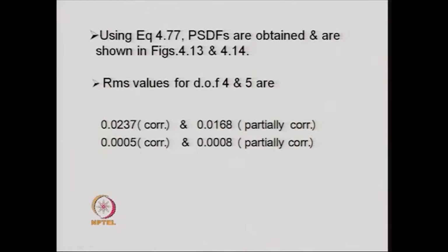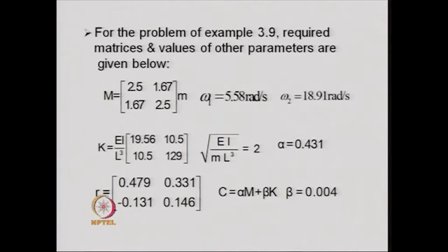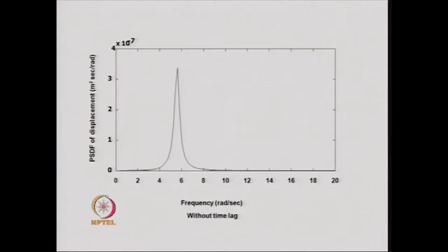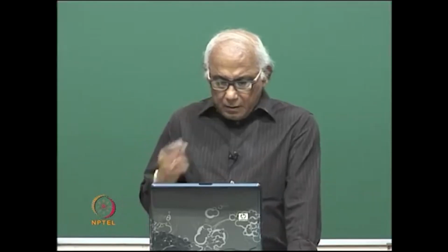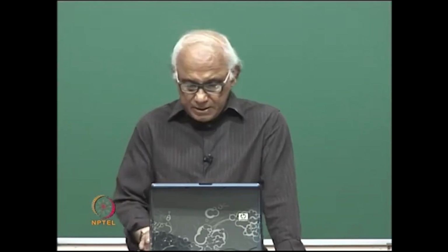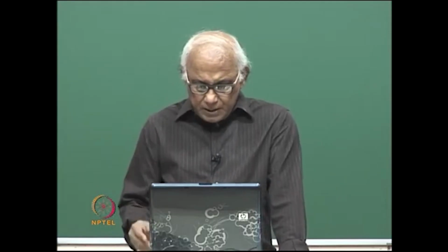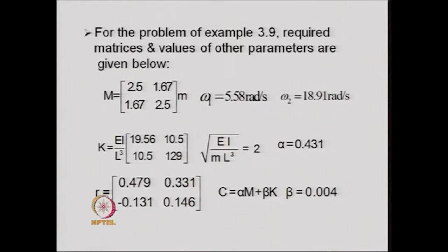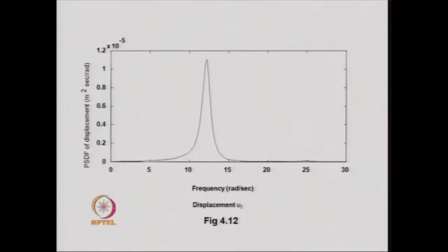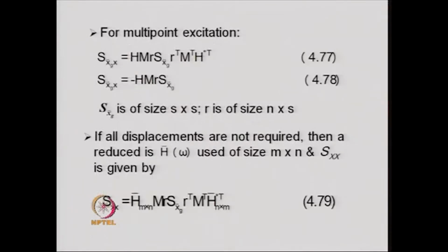Then for obtaining the value of the C matrix, after we have obtained the value of the C matrix, we use the usual formulation, that is, the equation that I had shown before. So, we plug into this equation, and in constructing the H matrix we have K minus M omega square plus i C omega, the inverse of that becomes the H matrix.